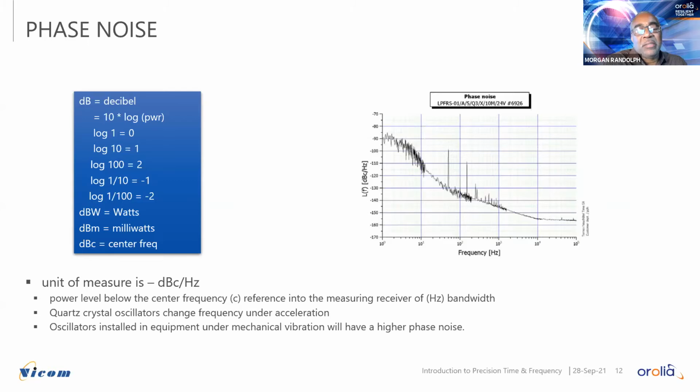I guess the most important line here is that quartz crystal oscillators change frequency under acceleration. If you're in a vehicle or in a sub, or in some type of motion as opposed to sitting in a rack, you're going to have the effects of that acceleration, and that vibration is going to impact the oscillator and cause phase noise.